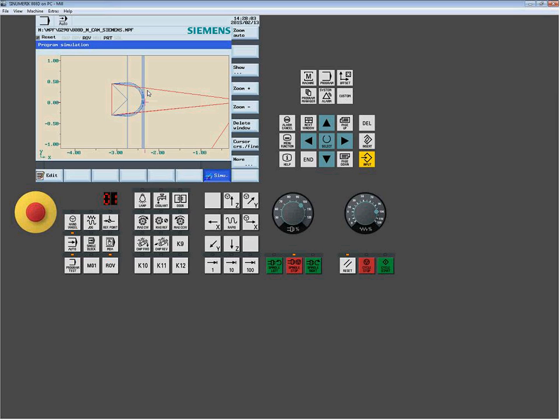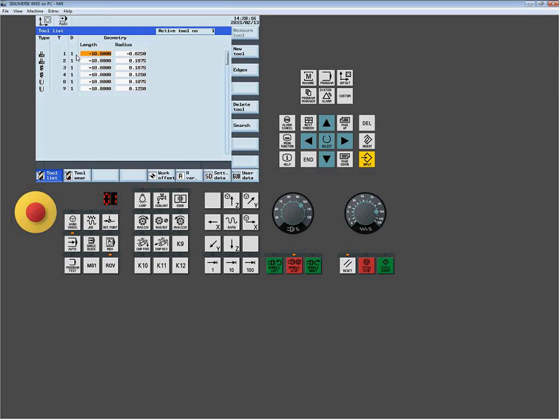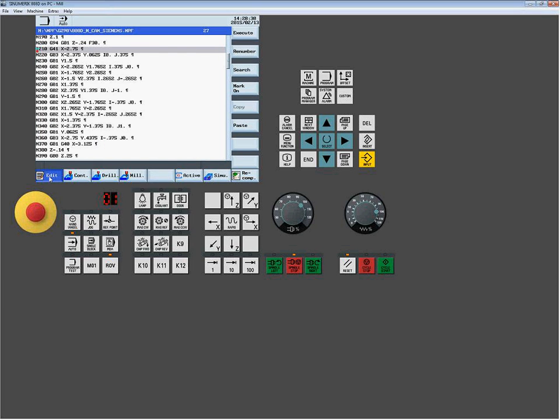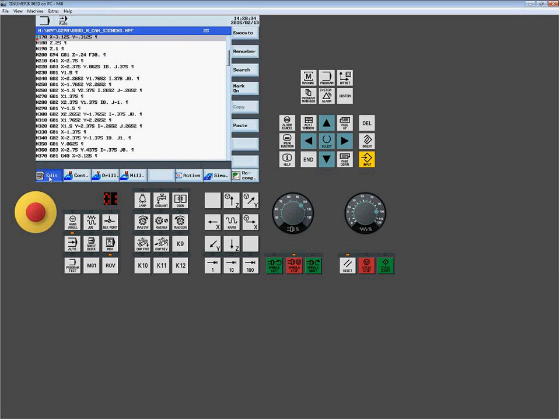If you get cutter compensation on and you need to change it because an end mill was undersized or oversized, you have to repost the entire file and bring it back down to the machine. Now, if we want the operator to put the correct radiuses here, we don't want this whole compensation we're seeing. Well, with Siemens control, we have a neat little feature, and we have the ability to modify offsets within a part program on the fly.